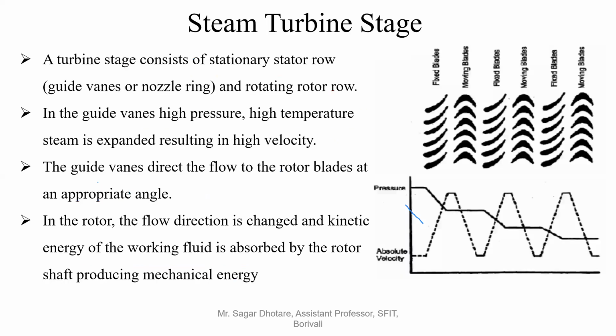Then by the steam supply, we can have a stationary turbine with constant speed, a stationary turbine with variable speed, or non-stationary turbines used in steamers, ships, and railway locomotives. There is one more type according to the type of governor used: throttle, bypass, nozzle, or a combination of throttle, bypass, and nozzle bypass.